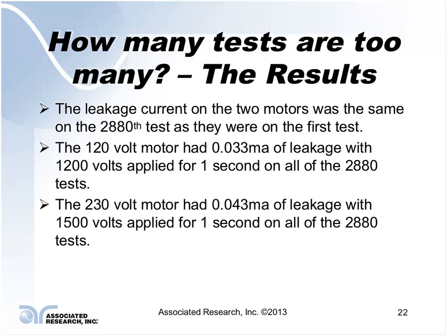So the first concern was, is this test in fact destructive or not? The first look was, yeah, repeated Hipot testing was, but in fact it was more an issue of the test potential that was being applied. If they had reduced the test potential based upon the altitude, it wouldn't have created a failure.